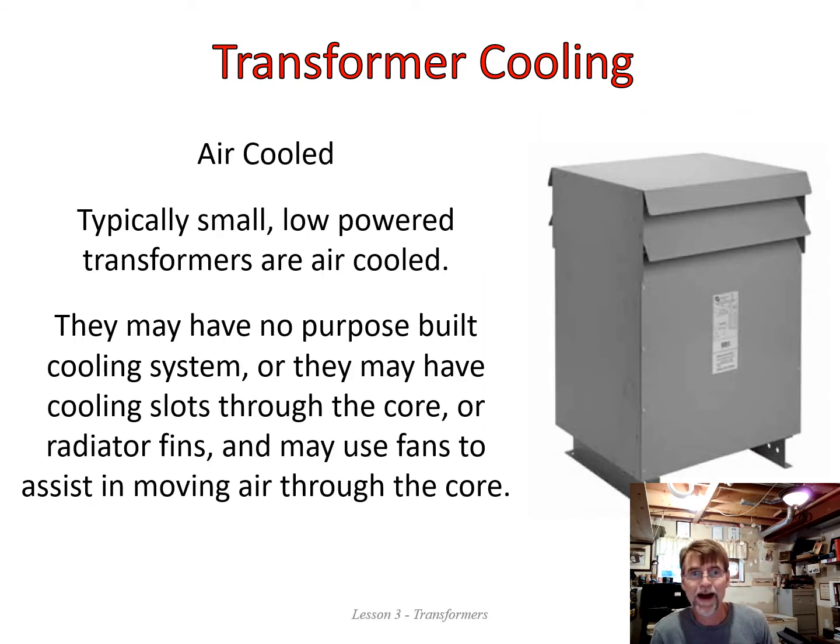So first of all, you have just simply air-cooled transformers. Typically these are small, low-power transformers, and we just use air to cool them. There may be no purposefully built-in cooling system, or they might have cooling slots through the core or radiator fins.